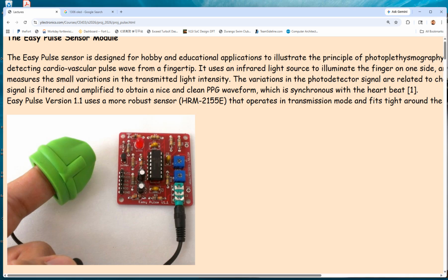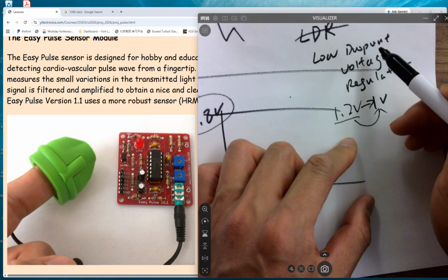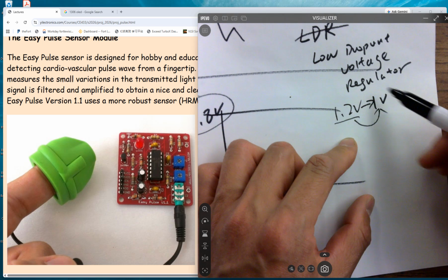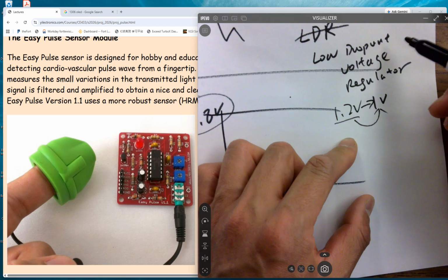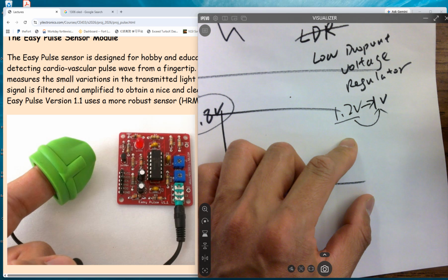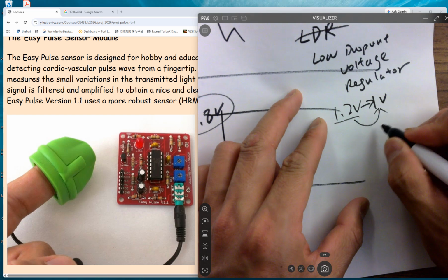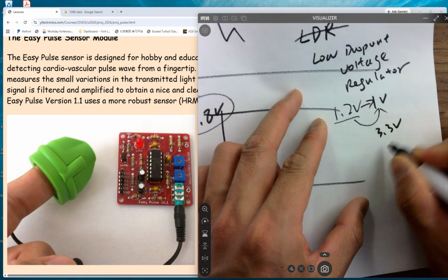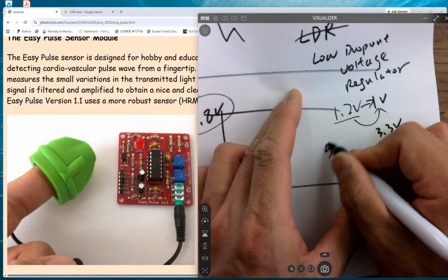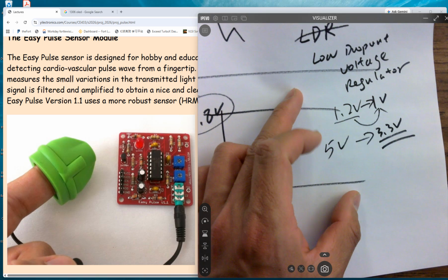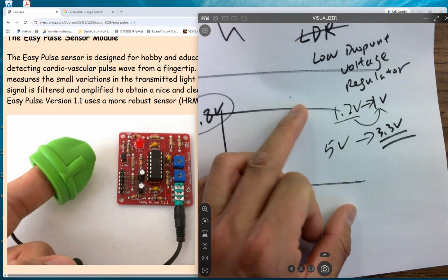Whenever the pads take that 3.3 volts into the chip, there will be voltage regulators. These are usually called regulators, but not low dropout voltage regulators. They could drop out like 1.5 volts easily. So when you are regulating 3.3 volts from 5 volts, that is still fine with cheap regulators.